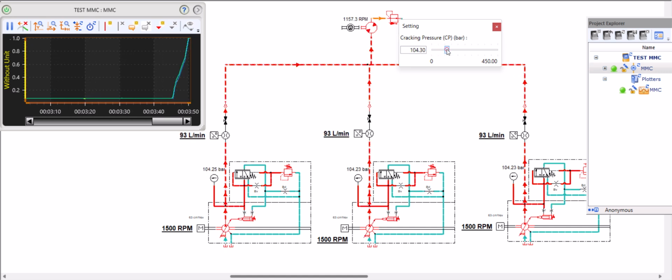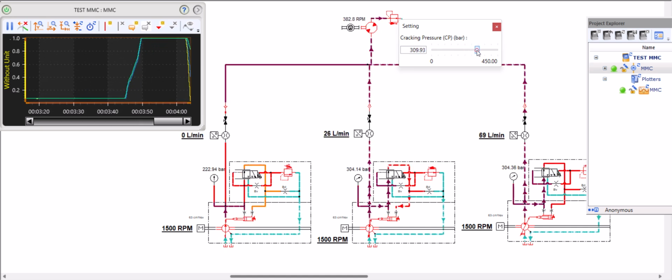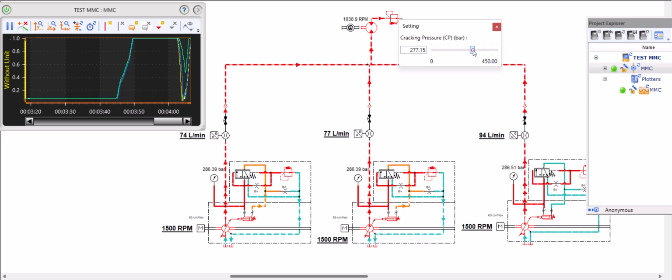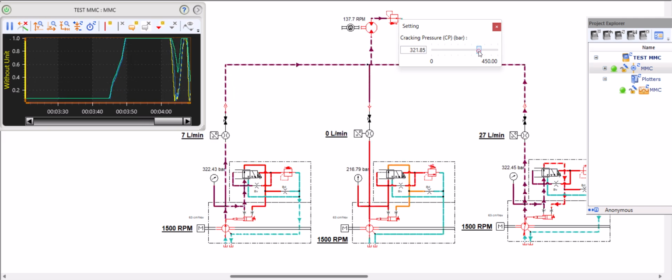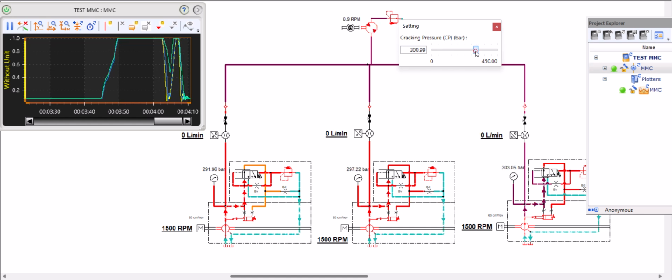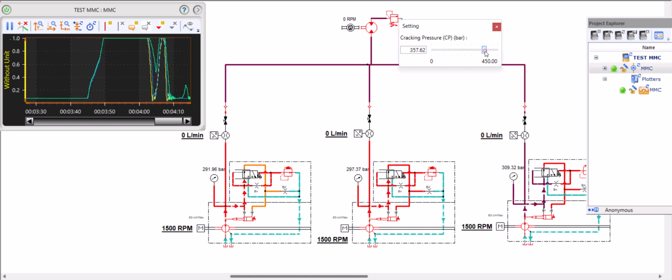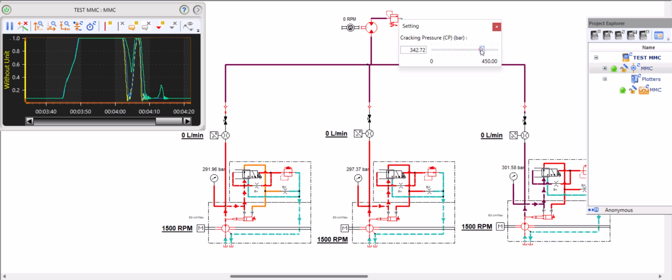As you can see, when the pumps are taken onto load, right now it is constant because all three are moving. Now I am increasing the load pattern. As I increase the load pattern, you can see the difference in the movement of the SwashPlates. This is definitely because one of the SwashPlates, which is at the lowest setting, will try and move fast as compared to the others.